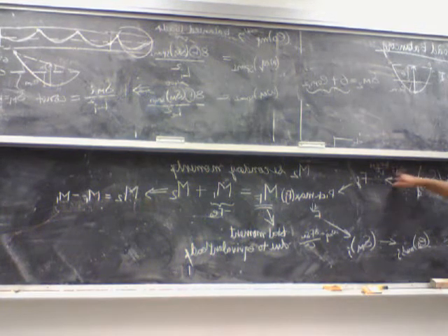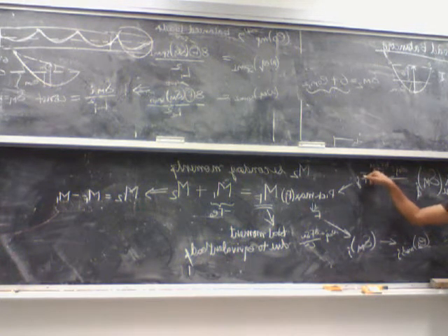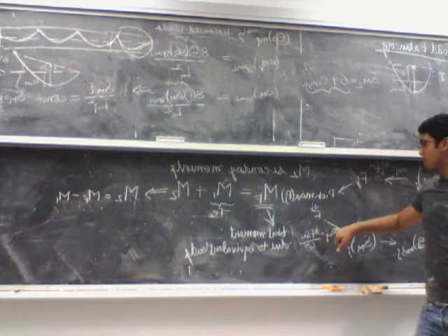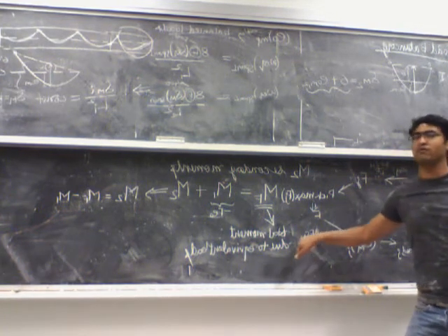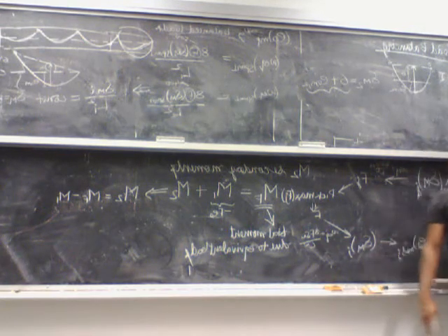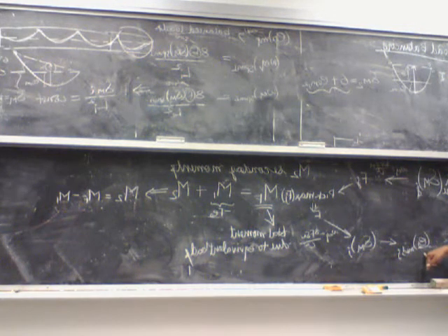So you actually use the same formula twice. But the first time you maximize delta M and find the value of F, and the second time when you come back, you already have the final value of F and you are calculating the delta M for each span. Once I have delta M for each span, I can find out the E naught for each span. And once you have the E naught at the mid span, you can actually define the actual profile.